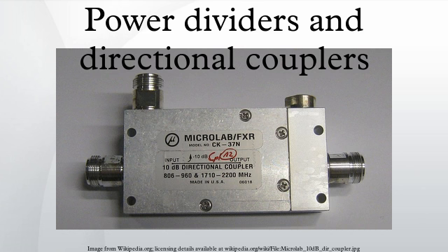Riblet short-slot coupler. The Riblet short-slot coupler is two waveguides side by side with the sidewall in common instead of the long side as in the Bethe hole coupler. A slot is cut in the sidewall to allow coupling. This design is frequently used to produce a 3 dB coupler.